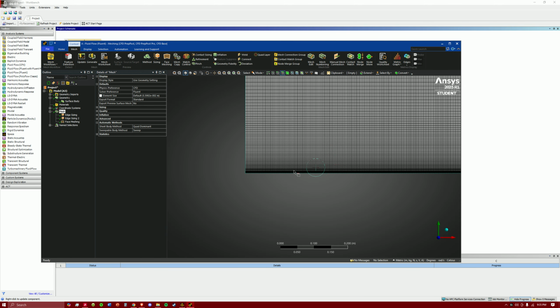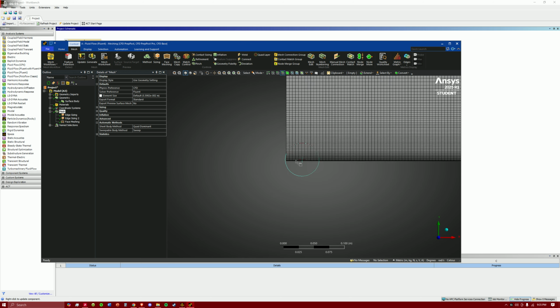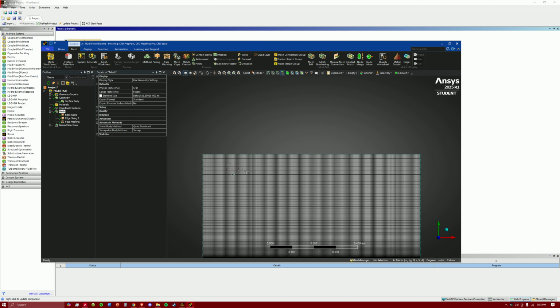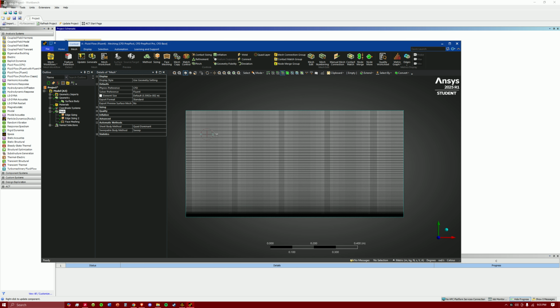Beautiful, isn't it? Here we can see you have this really accurate boundary layer down here. But up here, not so accurate because we don't really care up here. And if it's too fine up here, you're just wasting processing power. So you can make a more accurate model and save some of the processing power for what you really care about, which is what's down below.